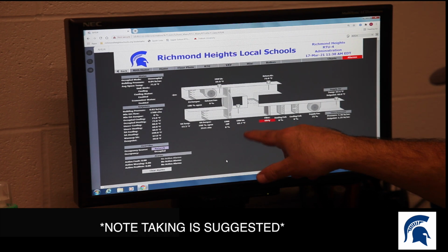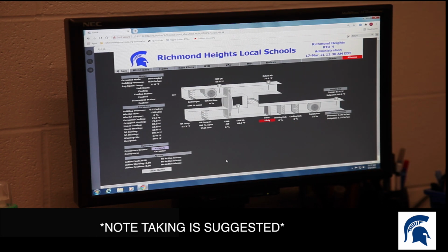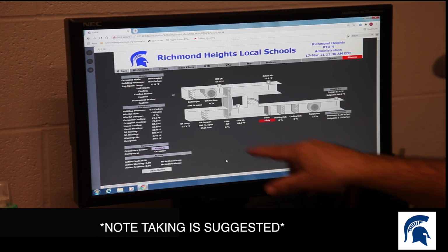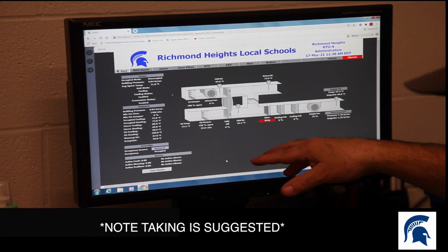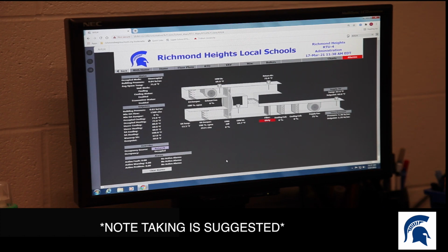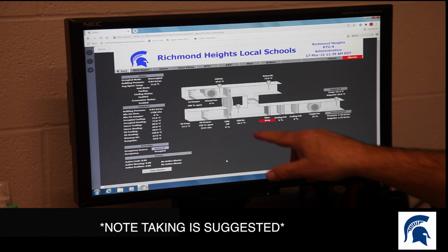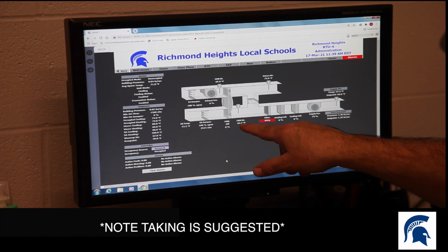Okay. I would say based on that temperature, it's not going around the wheel. It's just going through the wheel, and the wheel is just picking up whatever heat. Yeah, it's not spinning, but that can still cause it to pick up a little bit of heat. And then that's making you be above the 60-degree set point, that's why after the wheel it's 62.7.